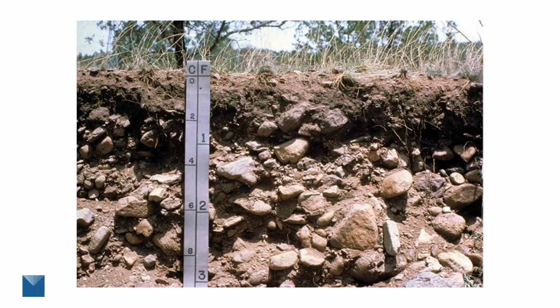But what if the profile looked like this one? Where and how do you make the measurements of conductivity? The material is extremely heterogeneous, with rocks having a high density and a high conductivity, and those are mixed with the lower density and lower conductivity soil in between the rocks. The heat will flow through the whole soil profile. But how do you assign a conductivity value for that profile?